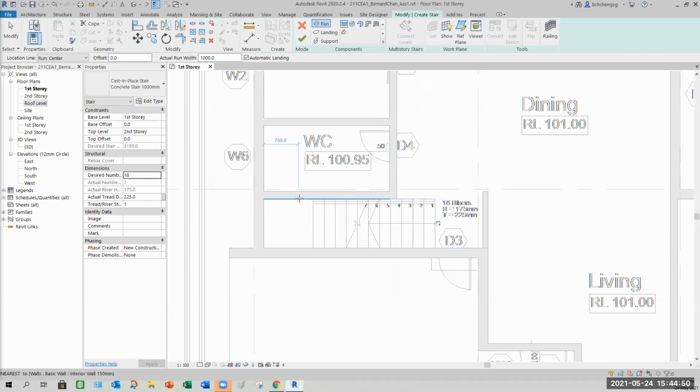Now here there is a problem. You can see that this particular staircase actually joins back to back. Normally for staircase, there should be a gap of minimum 100 mm. Only for this household, we got no choice because space is a factor.